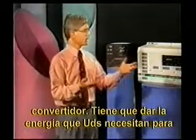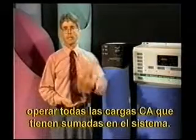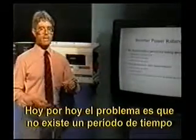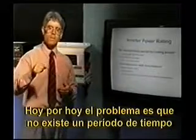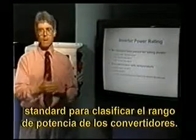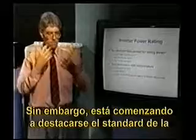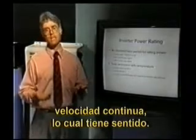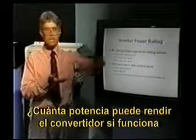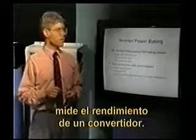It's got to be able to deliver the energy that you need to run perhaps all the AC loads that you might have added up in your system. The problem with inverter power ratings as of now, hopefully this situation will change in the near future, but one of the problems is there's no standard period of time for rating inverters. One standard that's emerging is a rating system that makes a lot of sense, and that's a continuous rating. How much power can the inverter put out if it's just continuously operated for hours and hours? But that's not always the way that inverters are rated.